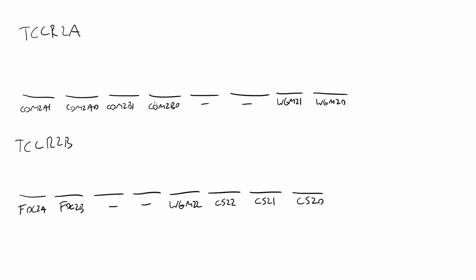So we're going to do a process of elimination here. Some of these bits are just blank and have no functionality, so they are just going to be zeros. Some of these bits I mentioned we don't need to worry about for this particular application, so we don't need these force output compare bits. And we are going to be using output compare B, not output compare A, so we do not need to worry about these two bits. They are going to be set to 0. If we were using the output compare A pin for timer 2, then we would need to use these bits instead. Okay, so that leaves us with these bits that we need to set based on the information we looked up in those tables.